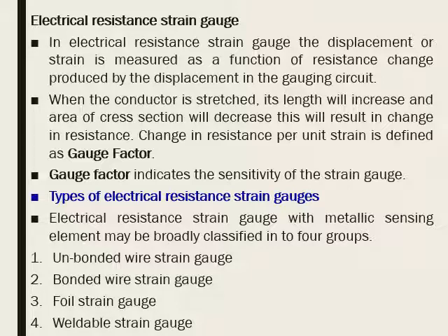Typically, an electric conductor is bonded to the specimen with an insulating cement under no load conditions. A load is then applied, which produces a deformation in both the specimen and the resistance element. This deformation is indicated through a measurement of the change in resistance of an element.